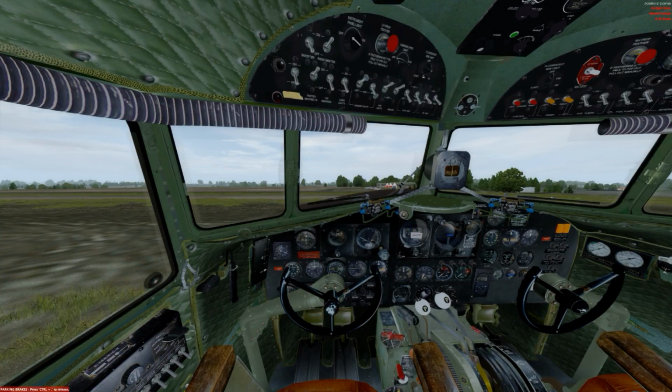Battery engaged. Navigation lights, close the doors. Lights as instructed, selected. On. Beacon lights on, as per your instruction. Seatbelt warning lights on. Cowl flaps switched on. Before start flow done, David.